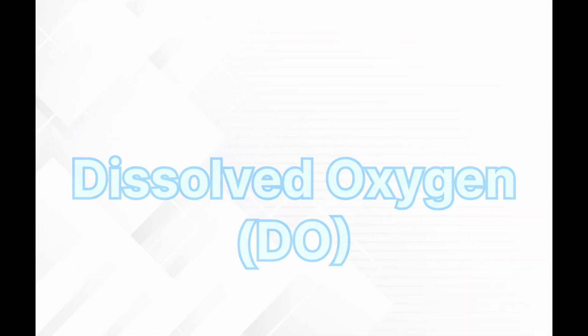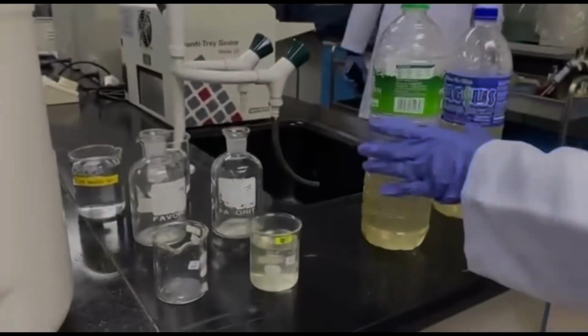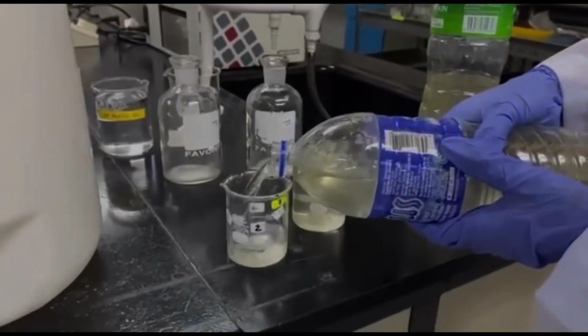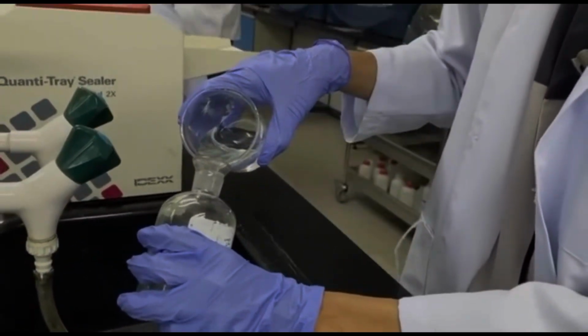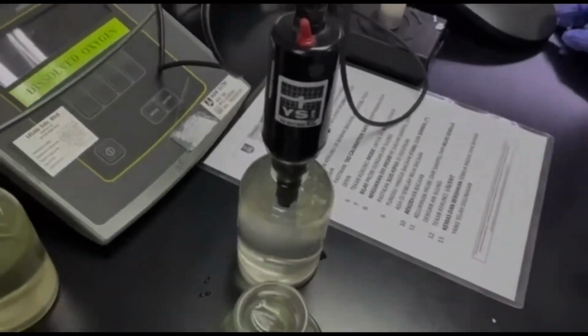For the dissolved oxygen experiment, we are taking 100 ml of sample and 200 ml of dilution water poured into a beaker and then into a glass jar. We then use a DO meter to take the dissolved oxygen reading.